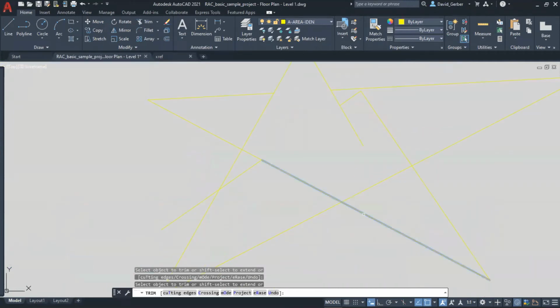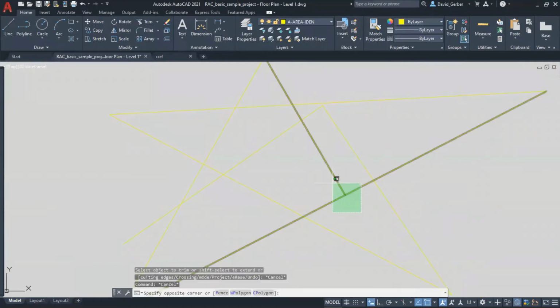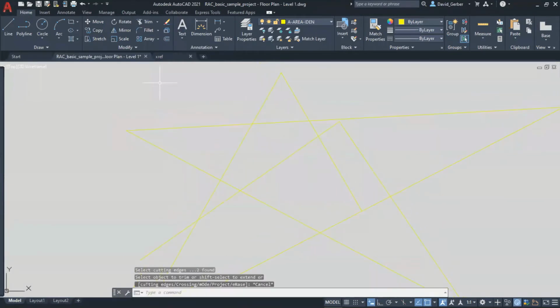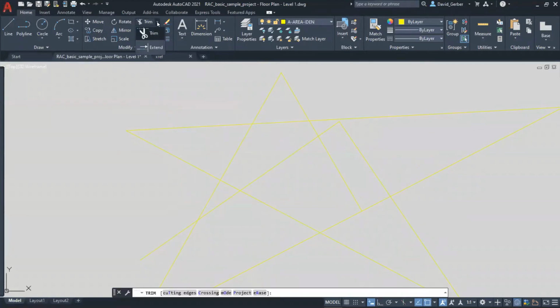Even if I hold shift to extend it, it's smart enough to replace them back again. So we don't have to do any of the selection like we had to do before, where we selected like that, then typed trim. And for those of you who press buttons, it's under the Home tab and the Trim here again, in that same area. It's just a little bit better now.